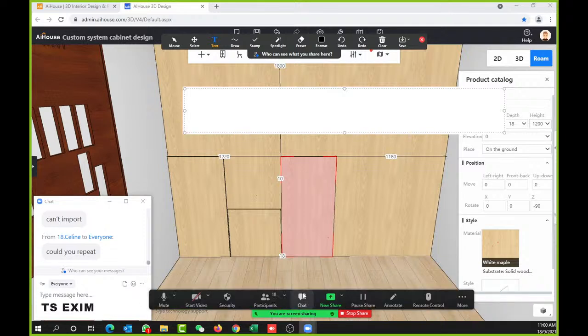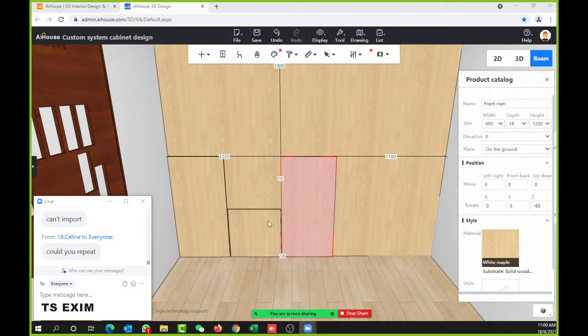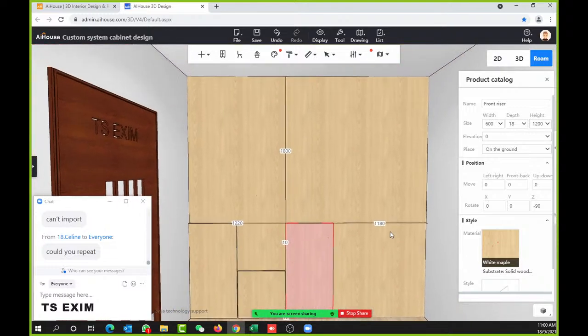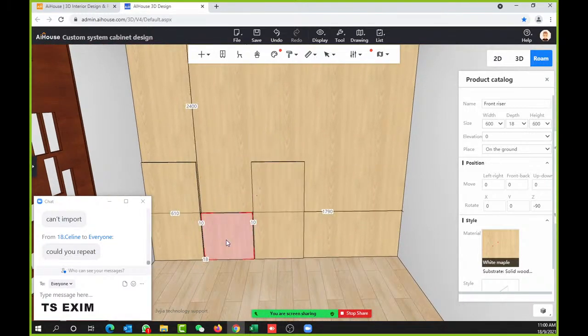Okay guys, time's up. So we continue. Okay, so to continue finish this wall panel. Very simple, we just copy, click on this one, press Ctrl V. Okay, then the distance here we add. First we add 110 mm gap for here, then add another 600 for the panel, then add another 10 mm gap. Okay, then press enter.